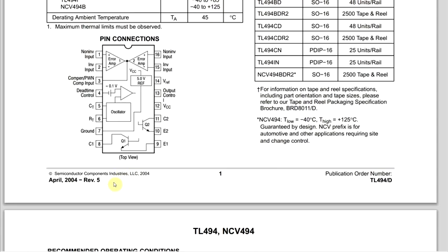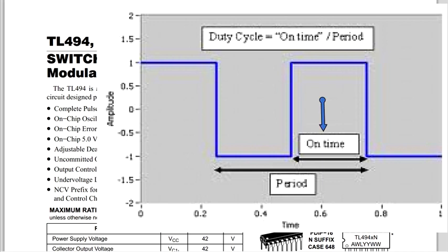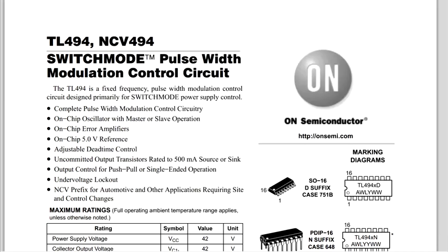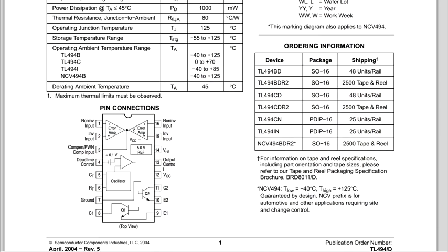TL494 is used in bipolar mode. You see the connections here, and those connections I explained in part number 1. TL494 uses the pulse mode with 2 outputs working in flip-flop mode, that would be bipolar. When one impulse is activated, one output is activated, the other output is silent, and the reverse.